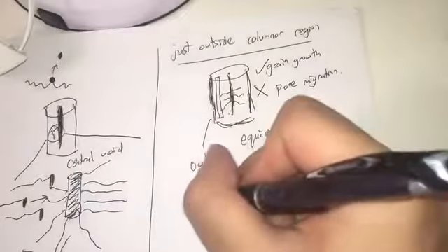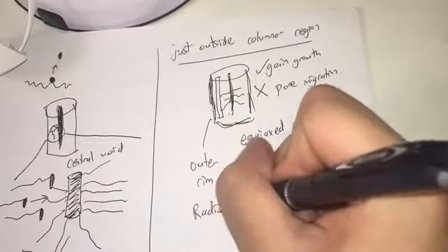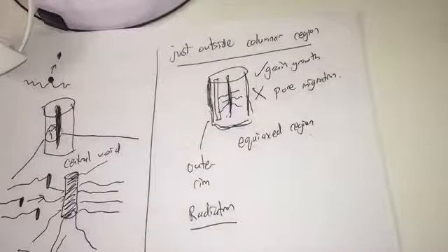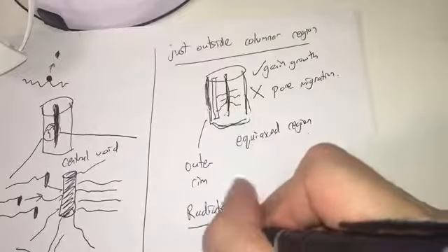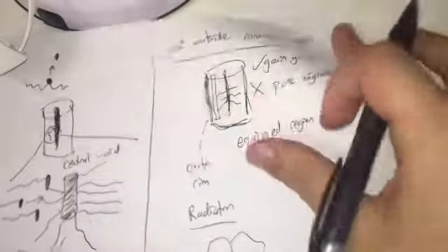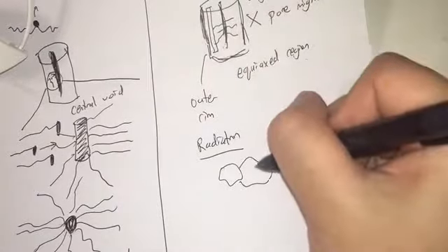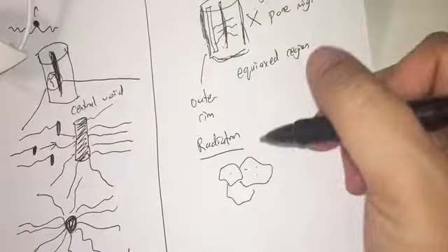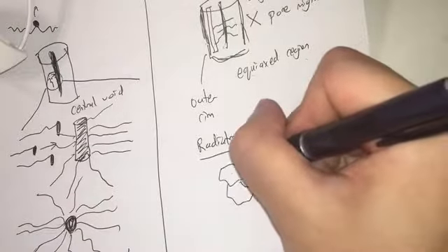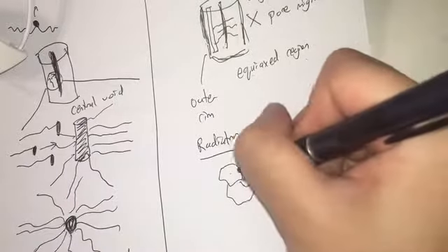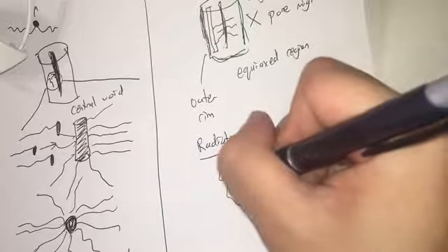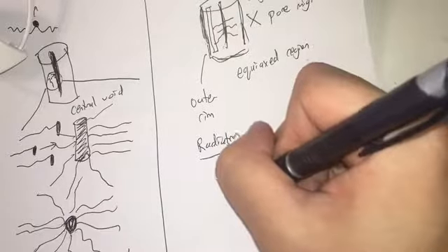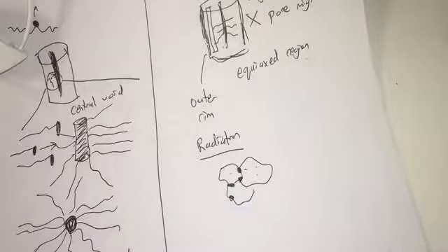just a side note, radiation. This is not a thermal process, but radiation will, of course, create vacancies and interstitials inside between each grain. And just like what we have in our FCC structure before, voids will start to accumulate at the grain boundary.